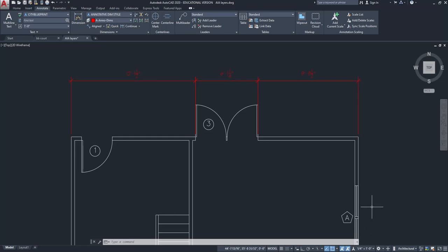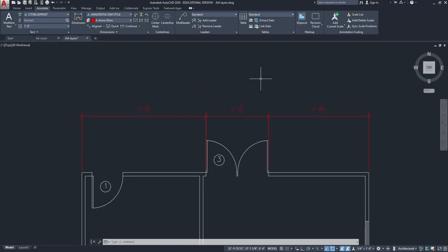Number one, how do we set our annotative settings? We'll talk about annotative settings a little more on Wednesday. The reason that the numbers are changing size is because at different scales, text needs to be a different physical height in model space so that when you scale it, it prints at the right size on the piece of paper. Okay? That was an idea that took me a really long time to understand. So I don't expect you to totally understand it right now, okay?